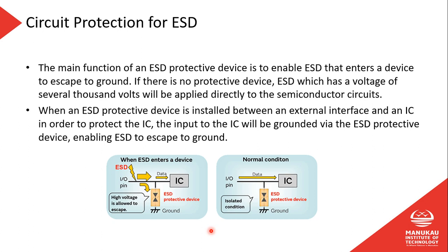We can see in the pictures here, right? We have a protective device here so that when higher voltages come through, this will open and provide a circuit to ground. It'll be a voltage dependent resistor. So when a certain voltage threshold is exceeded, maybe we would use some sort of Zener diode.